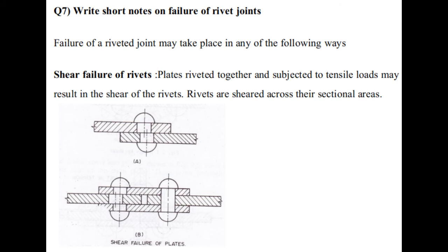Let us talk about another question that is also very important: write short notes about the failure of rivet joints. How many ways can the rivet joints fail? Let us discuss number one, shear failure of the rivets. For shear failure, please, as usual, note down the diagram. I will explain the shear failure.